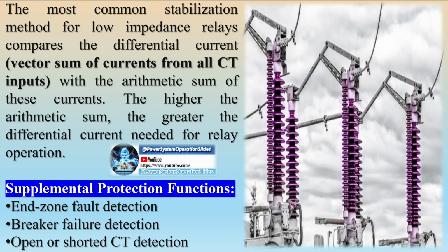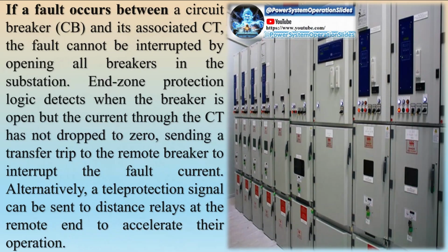The generic transmission system's key issues, i.e. reliability, operability, maintainability and cost, need to be addressed when designing a substation and selecting a busbar configuration and consequently a busbar protection scheme. At EHV-HV levels, solutions that provide a high degree of reliability can be justified. A busbar protection system should dynamically replicate the bus topology. It should also contain sufficient design flexibility to protect all existing bus arrangements.